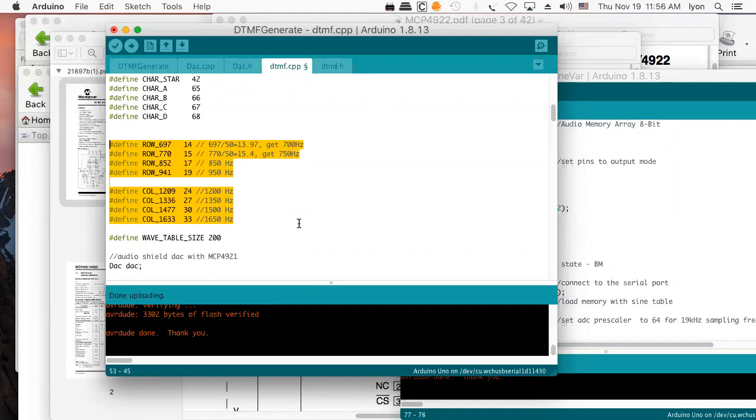They're just being pre-computed. So not a bad way to go, really. If you reparameterize it in terms of wavetable size and then double the size of the wavetable, you don't have to recompute everything because all of these numbers can be backed out from the size of the wavetable and your sample rate. Those are the two factors which you have control over.